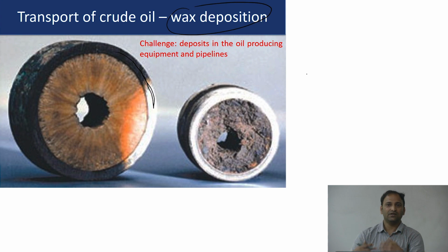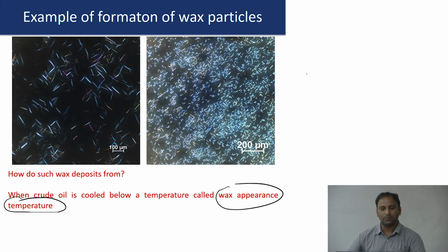First there's going to be some formation of a first layer of wax crystal. So it's not that this happens instantaneously. It happens over a period of time, but initially you could think of crude oil, at least when the temperature is around the wax separation temperature, as a homogeneous dispersion of such particles in a fluid.